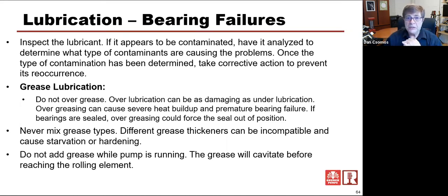You should not mix grease types if you're going to do grease lubrication. Some types of grease will interact with other types of grease, and they'll break down, and it may leave that grease basically unusable. It may gel, or it may drop the oils out of suspension and turn to liquid, and cause that bearing to run dry. So you should check and recommend what type of grease the plant uses, and match that. If you tell us what type of grease a company uses, we will do an initial charge of grease on those bearings to match that plant as well, the best we can. So don't mix grease types.